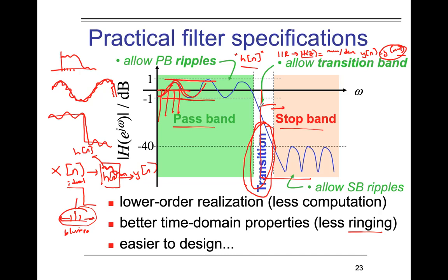What are you doing in your circuit designs arkadaşlar? How do you change the circuit design such that a higher quality factor will be obtained? Higher order filters, like second order, third order. Yeah, we can increase the order. If we increase the order arkadaşlar, this transition band will be narrower.